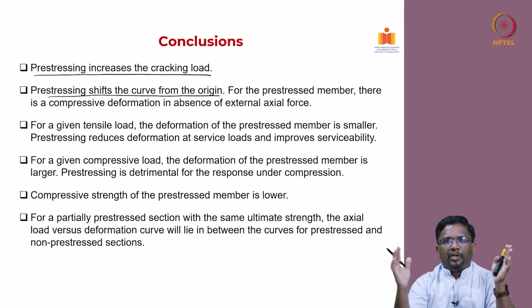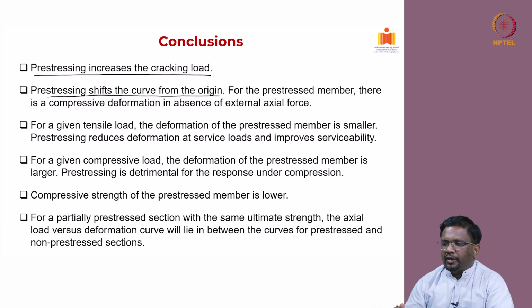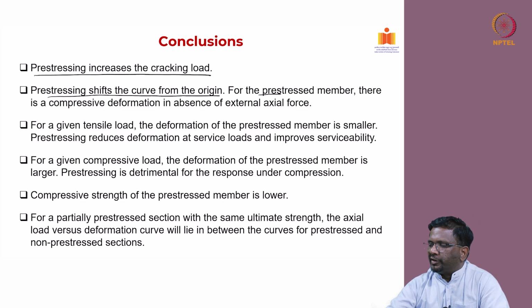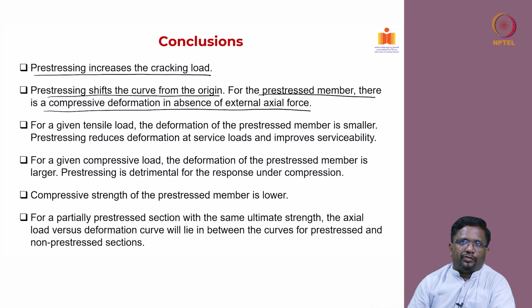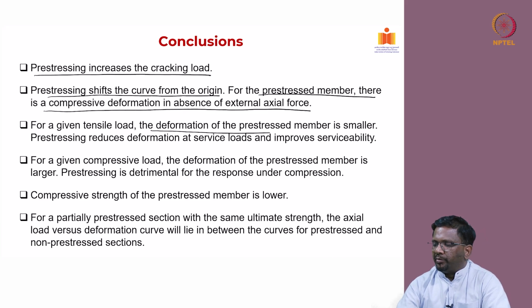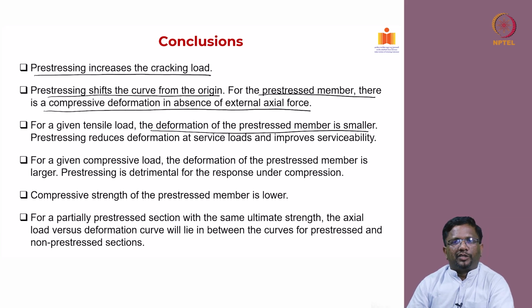So, because of pre-stressing, the member will always have some strains and deformations. For a pre-stressed member, there is a compressive deformation in the absence of any external axial force. For a given tension load, the deformation of the pre-stressed member is smaller. That means we have seen that pre-stressing helps me to reduce the deformation in a member.